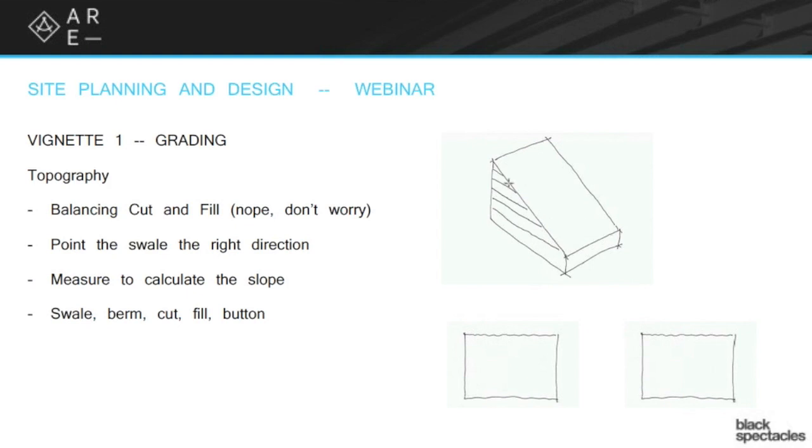If you imagine we have a little cutout of a slope of land, and each of these lines is representing, let's say, a 1 foot contour, like a 1 foot elevation level difference. And by the way, the contours don't have to be 1 foot apart. They could be 2 foot, they could be 5 foot, they could be 10 foot. They could be 1 millimeter. It depends on what scale the issue is. If you're looking at maps of the Rocky Mountains, they'll often have them in 25 or 50 foot contours because the scale changes so quickly. But generally on the exam, it's probably going to be a 1 foot contour, but you should always check to make sure. So let's say these are 1 foot elevation differences.